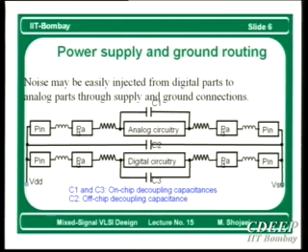Now, shielding. See, what we do in shielding: suppose you have a signal line, okay? This is a signal, and this is also another signal. This couples some noise onto this line because of coupling capacitance. So I want to shield this in such a way that it gets protected, right? In the conventional case, for example in BNC or coax, we put a cover, which will be ground, VSS. So it is shielded. Here I cannot make a cylinder.